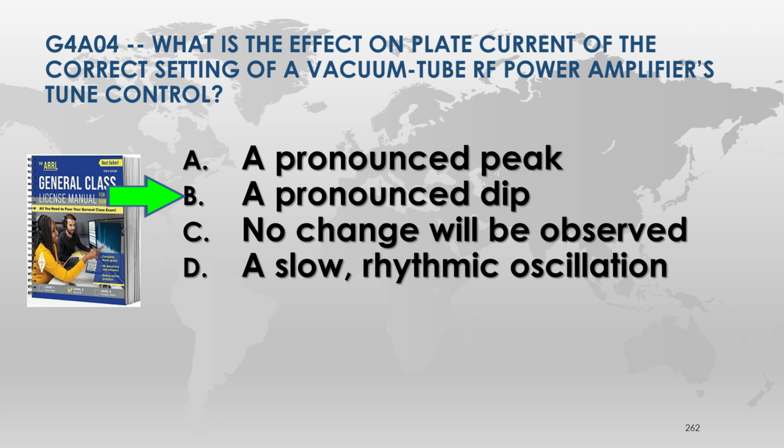When you get to the right frequency, you're going to see that dip as it gets to a resonant level with your antenna. Then you can increase your settings to get that back up to your correct power level. But that dip is important because it indicates when you've got your resonance going. It's a dip in the current. Yep. Using less power to push it out. Yeah, that works better.